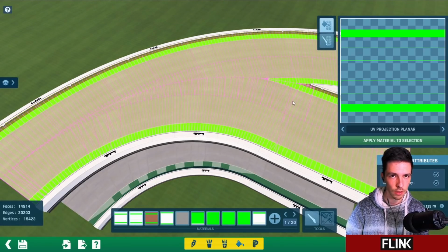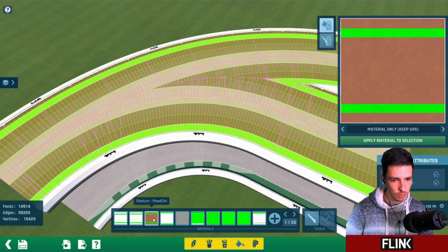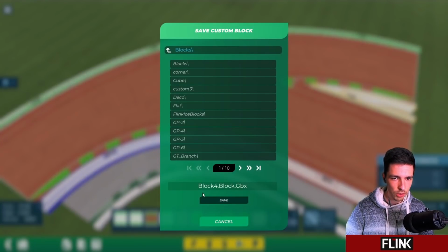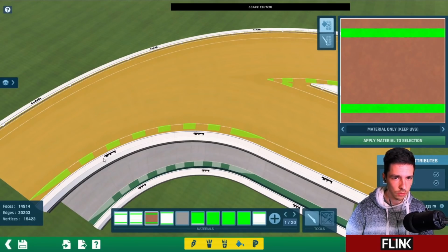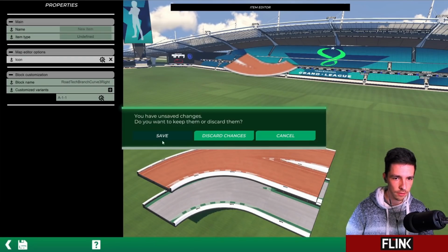And that's why we did the 3 times clicking and then Ctrl Q, because now we can go to the left projection and do the keep UVs mode. If we click it now, aha, now this looks great. But let's maybe do dirt. Give it a good name. Go 1 step back, maybe add an icon if you want.